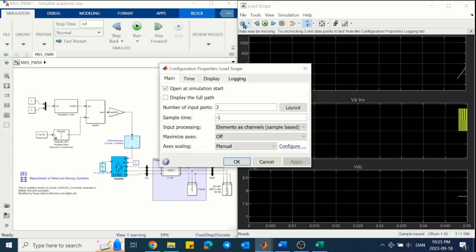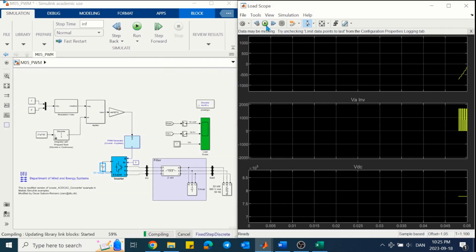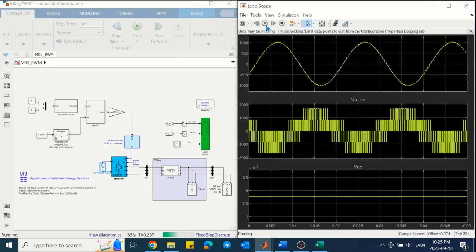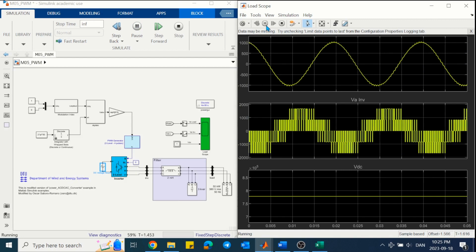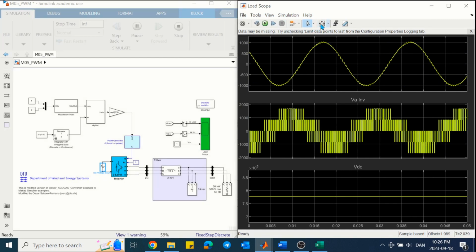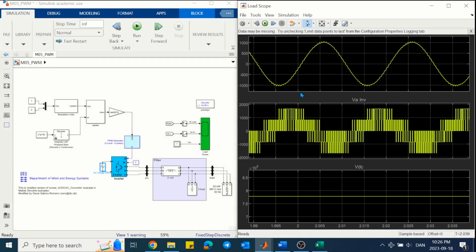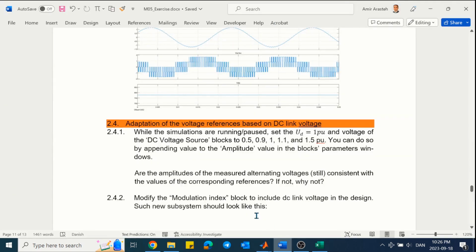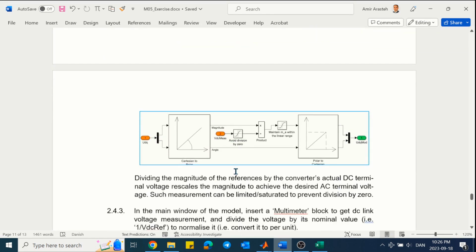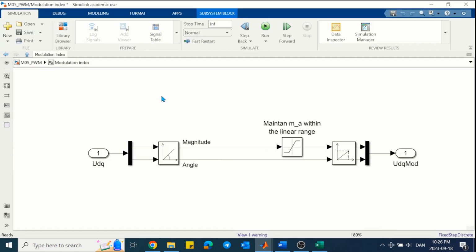We can see that it's covering a very small area, not 50 milliseconds. We need to set the sampling time to Ts to make sure that it has an equal sampling time as our simulation time step. We can see that the logged data is equal to our time span of 50 milliseconds. In the model that you have received in the exercise, we already considered this point in the setting of the scope, but to make sure, just try to check it on the scopes.